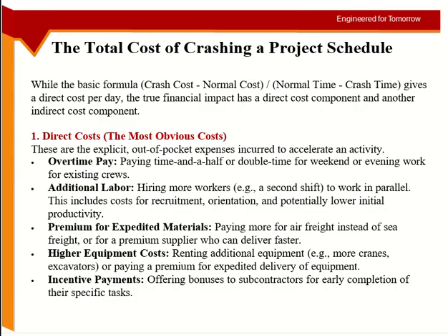It can be the use of materials which are better suited for quick work. For example, quick hardening cement. We have the normal hardening cement, which will take maybe 3 days to harden completely with curing, and then we have the quick hardening cement, which may do the job in one day.